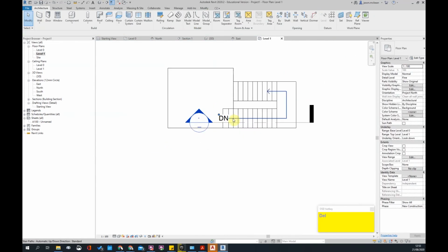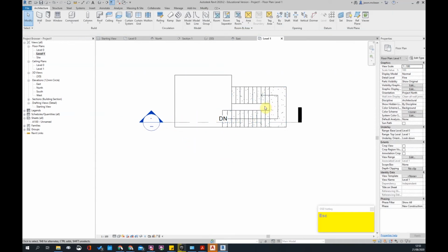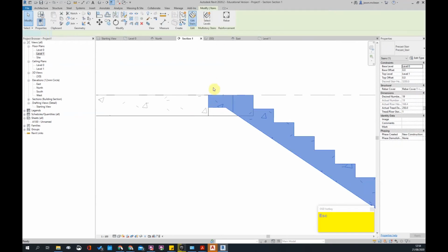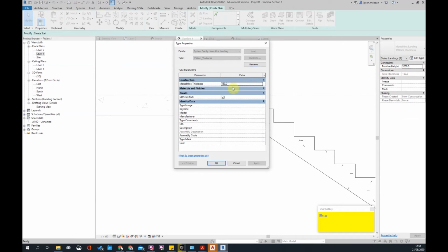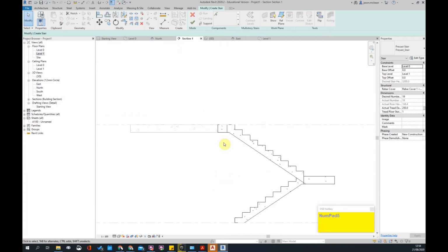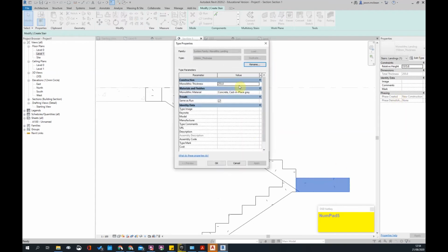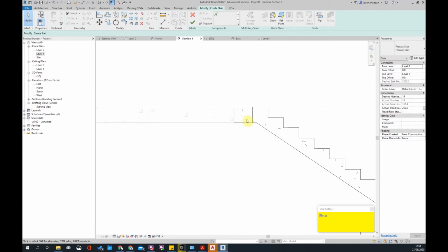You just need to change the material of the stair so you don't get the same look and feel as you do for the slab. So in essence, I just need to change that landing. So it's stair, if I click the landing here and I say edit type, here I can make this a 255 and I can duplicate it, 255. Press OK. Okay, let's change this one as well. Okay, so you need to make them different, but here it will solve this issue here.